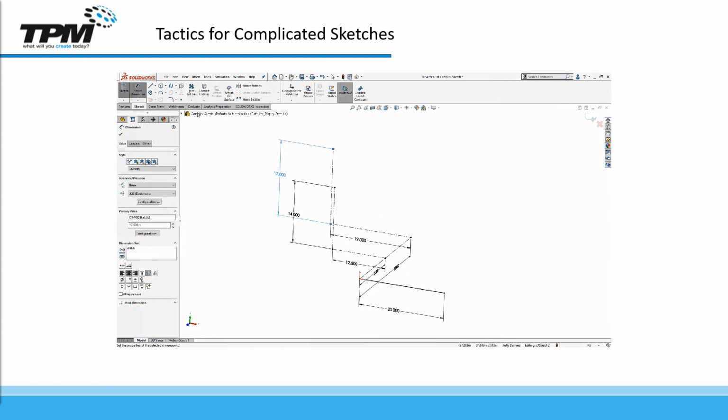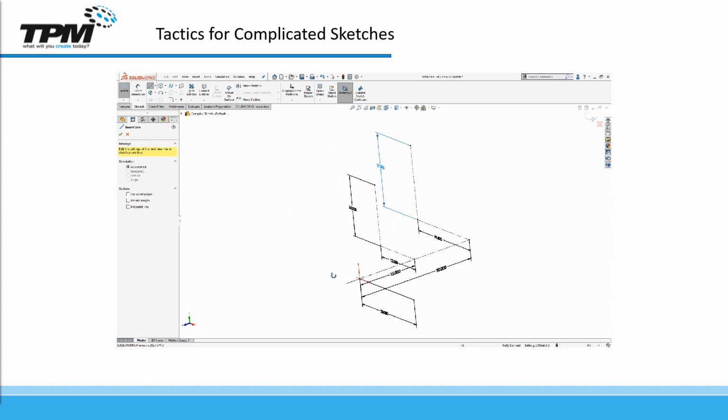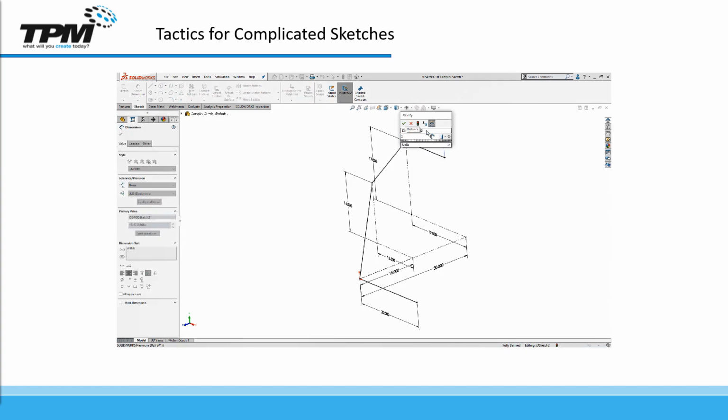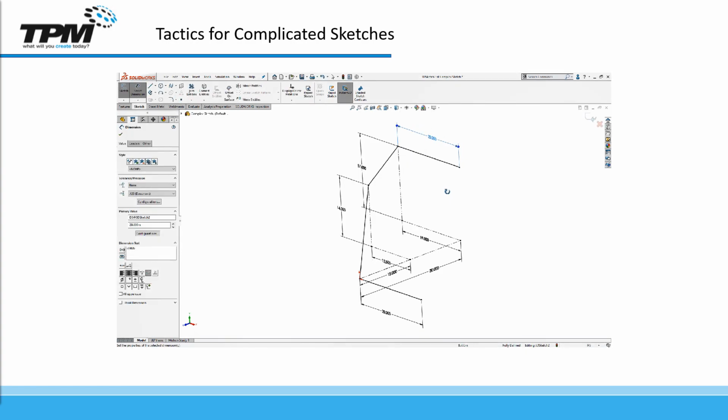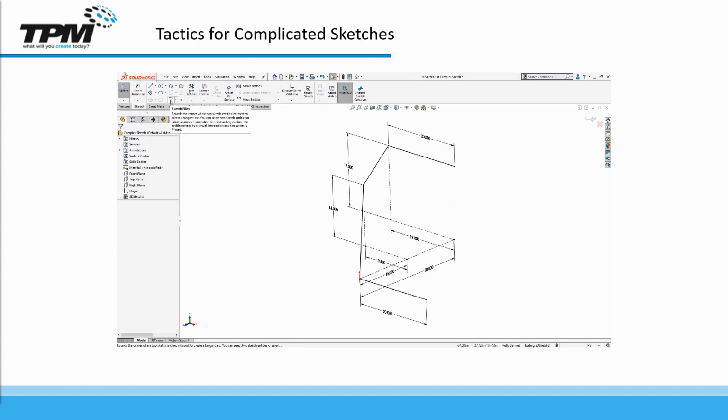So now we have the apex points for our complex arc. So let's tie them all together with lines. So I'm going to go to the first point, then to the second point, and then I'm going to finish it off with another piece that is exactly like how we started, another 20-inch piece. So assign my value there. So what we have is a complex arc in each apex individually dimensioned.